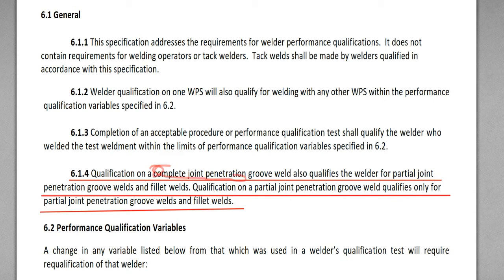So if you did the qualification test with a complete joint penetration, full penetration butt joint weld, then you can be qualified for partial joint penetration, not a full penetration groove weld, as well as fillet welds.